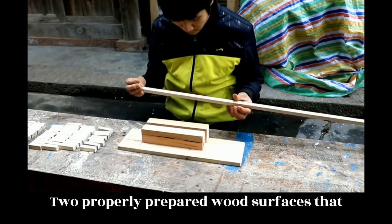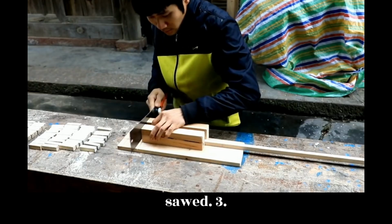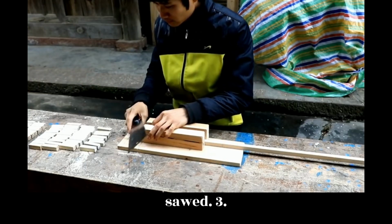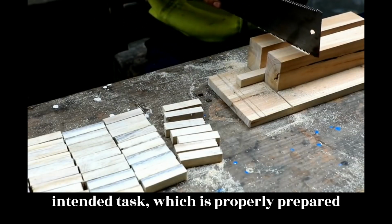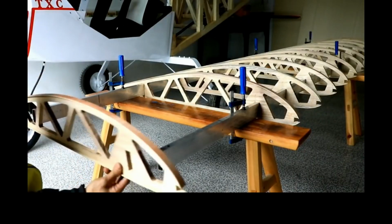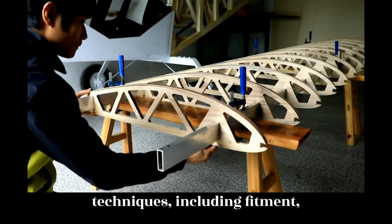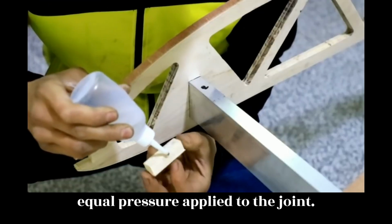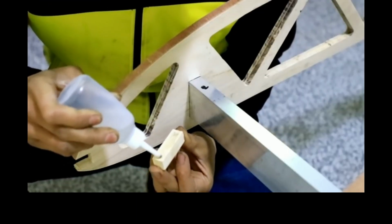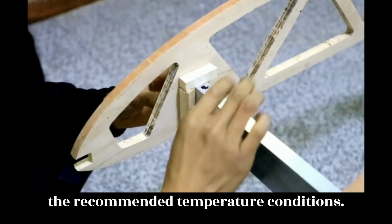2. Properly prepared wood surfaces that are machined or planed, and not sanded or sawed. 3. Selection of the proper adhesive for the intended task, which is properly prepared and of good quality. 4. The application of good gluing techniques, including fitment, recommended assembly times, and adequate equal pressure applied to the joint. 5. Performing the gluing operation under the recommended temperature conditions.